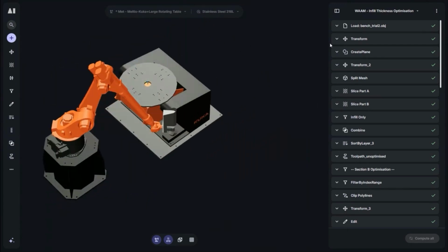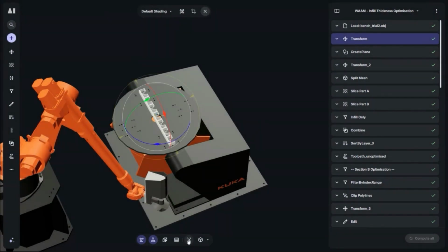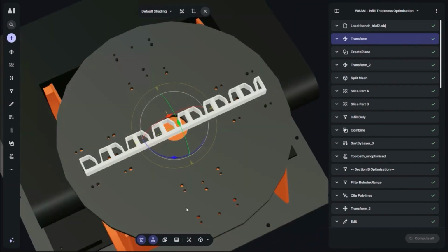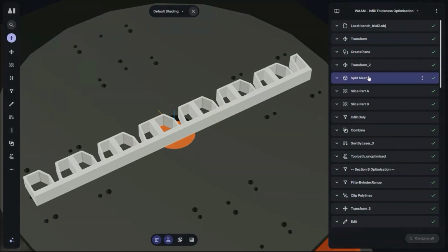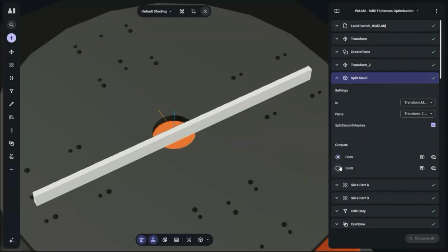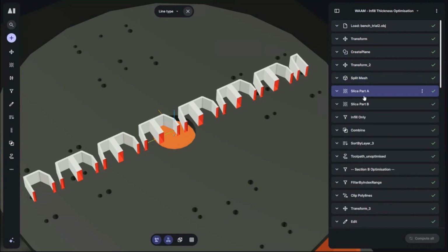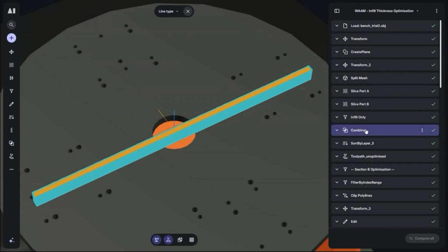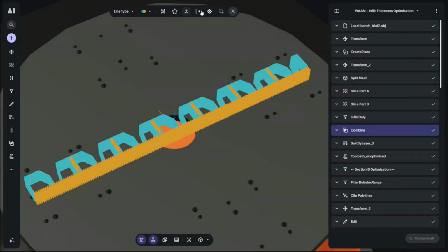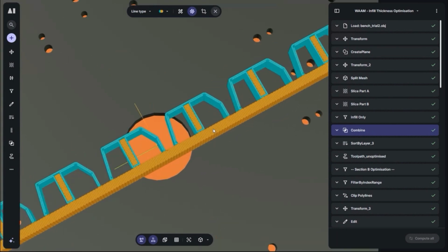for infill optimization earlier. We can do something very similar for metals as well, using different kinds of printing parameters. Like we said before, we have some limited CAD ability in the software. So here I've actually used a plane to slice this, or to cut this part into two halves, and with some different slicing settings. If we combine those two halves, you can see that we have this kind of weaving and contour combination.